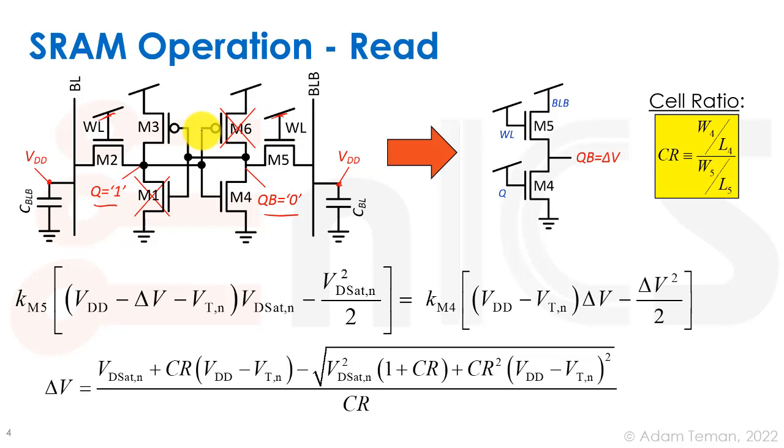And between the two sides, we can draw a schematic that shows us what's going on. With Q and Q bar as our output, if we look at Q, we're pulling up to VDD over here, and it's not actually trying to fight with the one that's over here, but when we have VDD over here, we're trying to actually pull up this side.